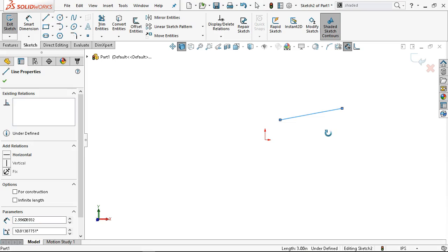And when I hold down the middle button or the scroll wheel, that is my rotate. See if I can remember these. Holding down the control button in middle is a pan, and the alt is rotate about the plane that you're in.